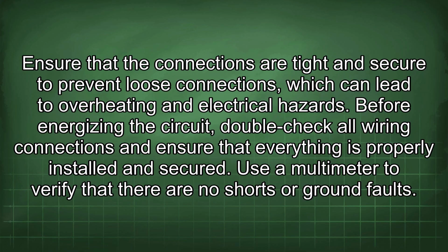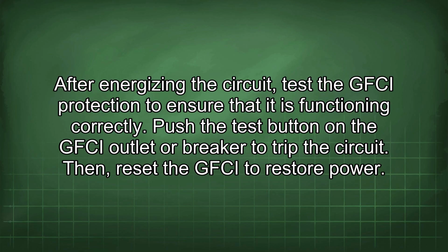Before energizing the circuit, double-check all wiring connections and ensure that everything is properly installed and secured. Use a multimeter to verify that there are no shorts or ground faults. After energizing the circuit, test the GFCI protection to ensure that it is functioning correctly.